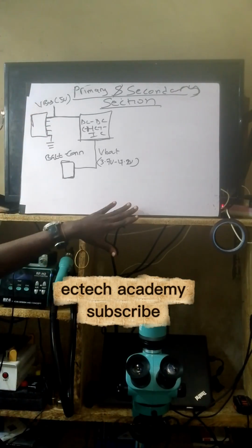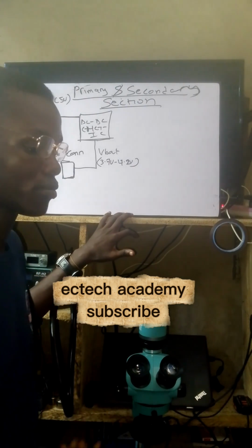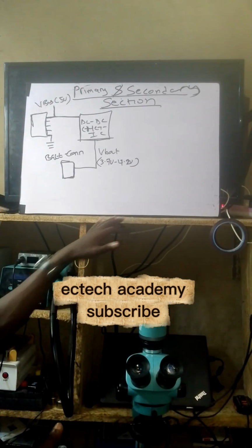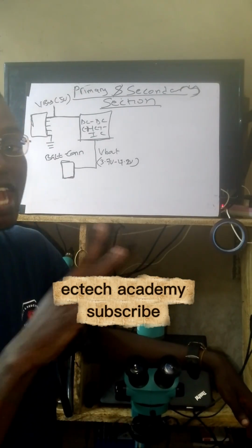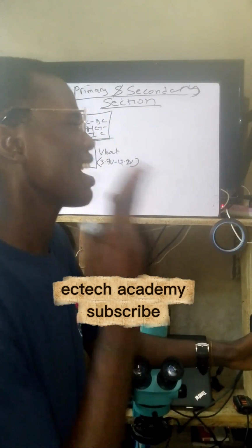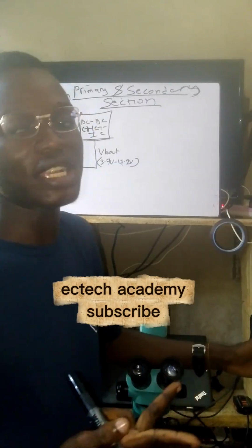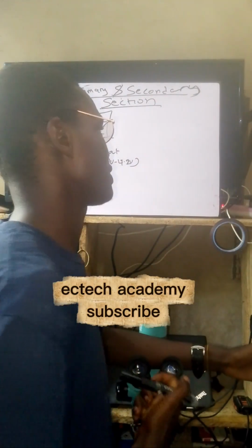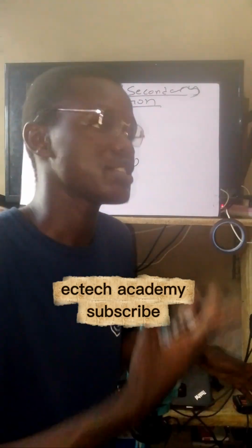Especially for some phones that are coming now, there are some latest phones that have two DC to DC ICs. One IC, if I remember on the schematics, is called the switching IC, that's the DC to DC IC, and one we call the master charging IC. The switching charging IC is also called the slave charging IC.